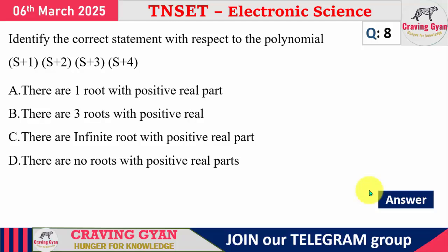In the 8th question, what they have given is to identify the correct statement with respect to the polynomial. There is 1 root with a positive real part, they have given; it is wrong. Now look at the things, all the poles are lying on the left half of the S plane. One pole is at S plus 1, which means S minus of minus 1, so the pole location is at minus 1. Next pole is at minus 2. Another pole will be at minus 3. Another pole will be at minus 4. So, option A is wrong. There are 3 roots with positive real part. There are no roots with a positive real part.